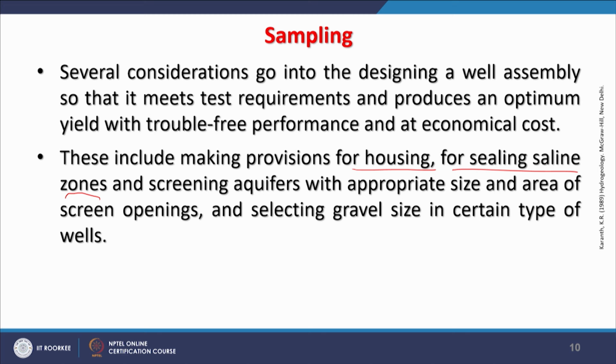So, these considerations include the provision for housing, for sealing saline zones, sometimes one may encounter this kind of problem, and screening aquifers with appropriate size. All pipes are not blank pipes; some pipes, at certain lengths where water is available in the aquifer zone, are perforated, and that pipe is called the screening. So, screens should be present in the pipes, and this is in the case of unconsolidated materials or rock formations, but in consolidated rocks like in hard rock terrain, such things may not be required.